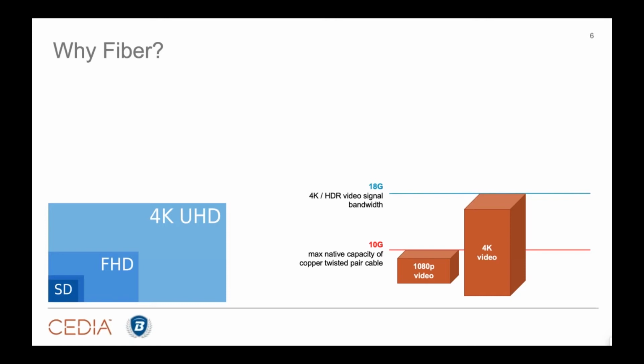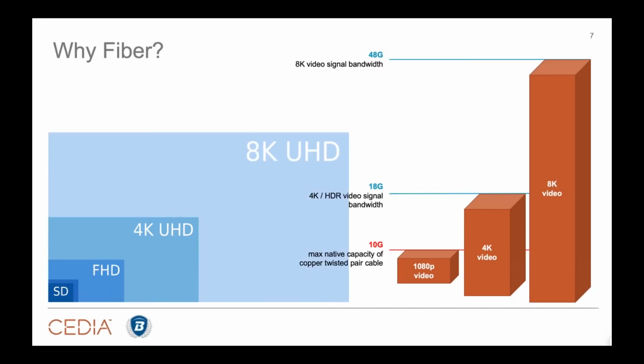You gotta take the 444 color space, compress it down to 420, get your 18 gig signal down to about 9 gig, transmit it, then blow it back up. It's possible. Not ideal, but possible. Often what you'll see is some color banding, some artifacts, a little bit of latency on the processing, but it is possible. But now we have an issue.